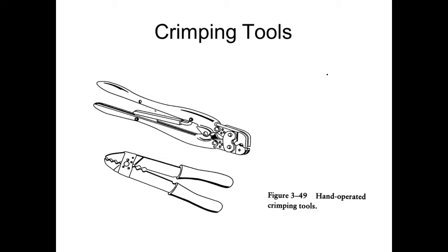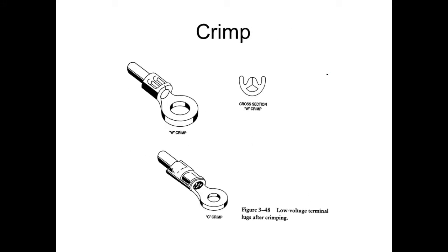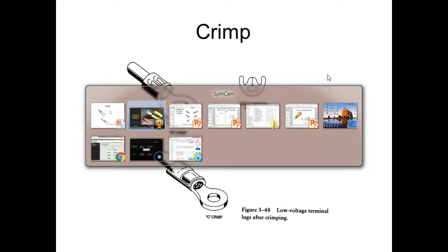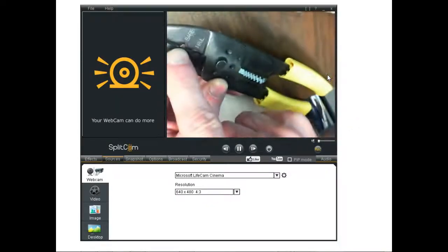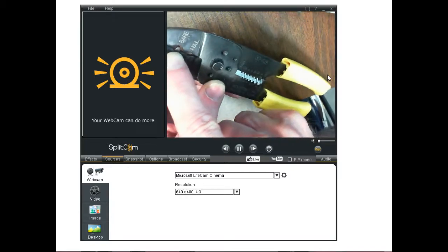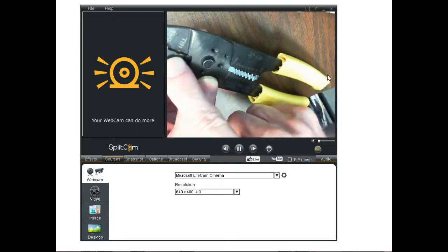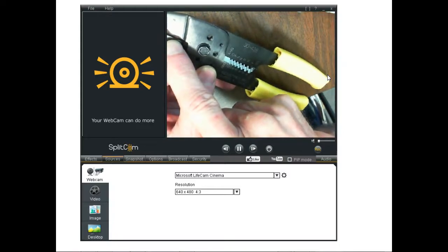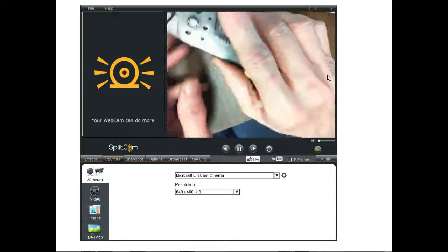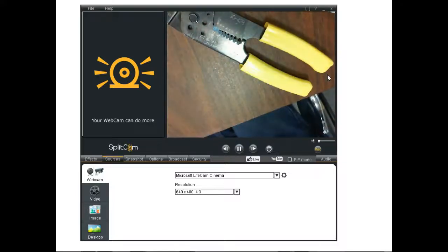So these are different crimp tools. Of course, these are the ones that we're using. We have some that flatten crimp, but we don't want to do that. The best crimp when we crimp the wire is one that's got this notch in it right here, right? And that gets the best crimp on the wire. And then we'll move back to the insulation and crimp the insulation. Make sense? Everybody okay? So cutting that to the right length is really important.